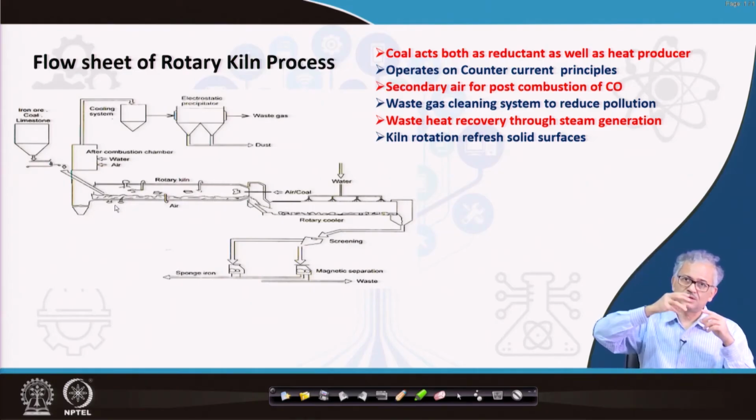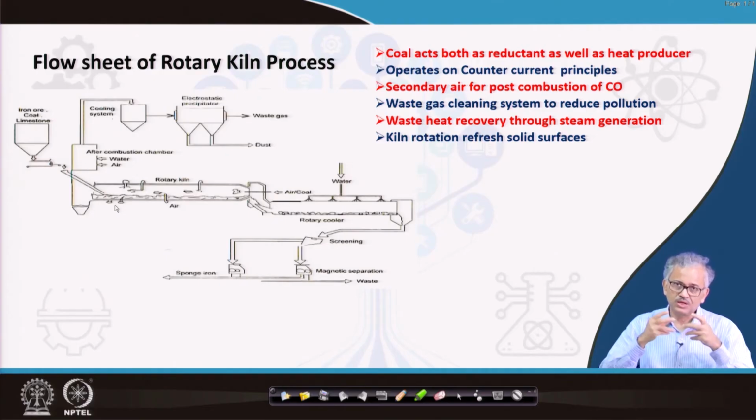And then kiln rotation. Now, as I said, when the feed is coming in and the kiln is inclined to some extent for gravity, such that by gravity the solid moves from one end to the other. And the thing is that the kiln is rotated. Why this rotation? If it rotates, then basically the surface of the raw material gets renewed every time, both with respect to the wall, because the heat is coming through the wall also, through the wall heat is coming to the solid, okay.